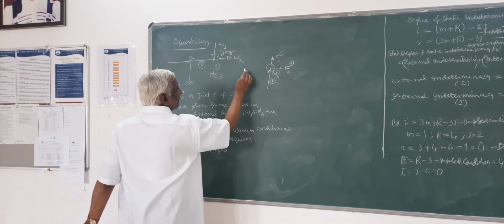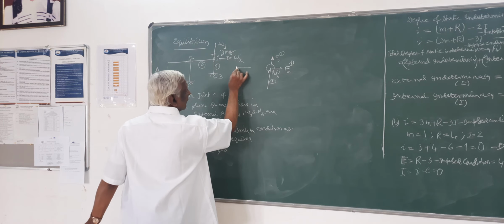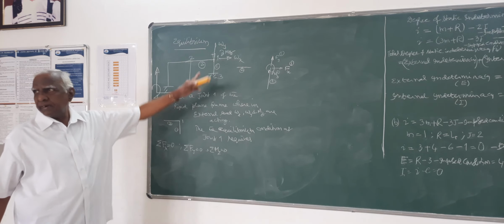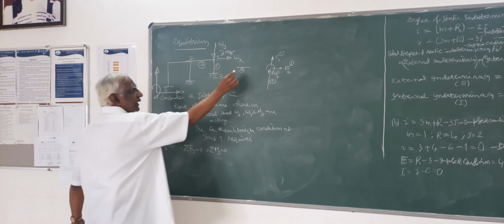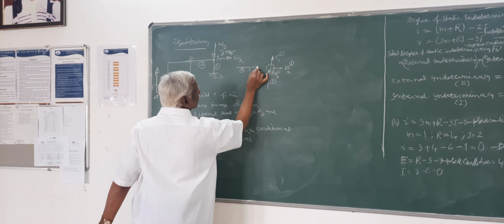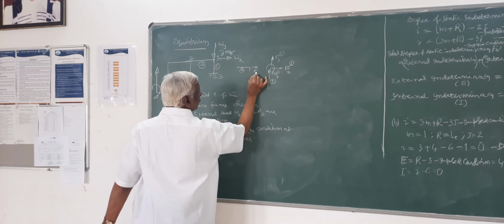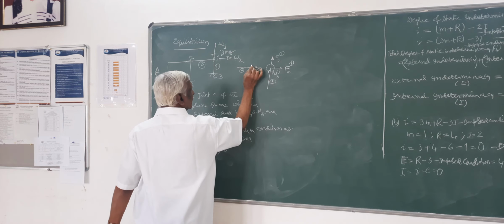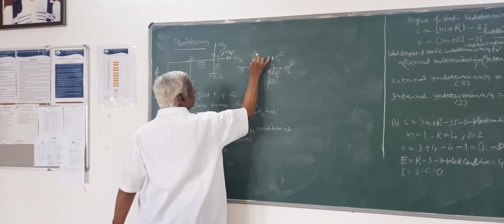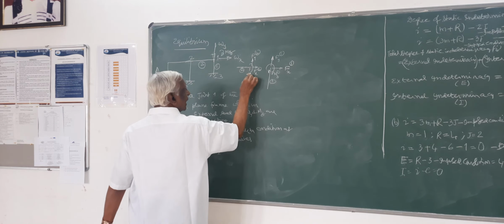Likewise, at the same joint 1, I have another member, member 2, meeting at joint 1, and here this member has an axial force Fx2 as the internal force, and also Fy2 and Mz2.